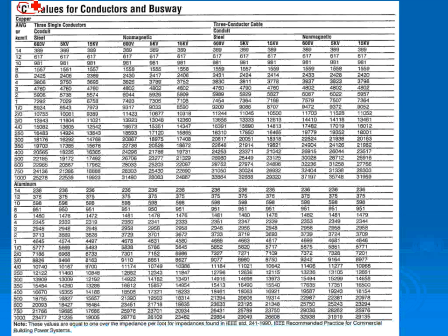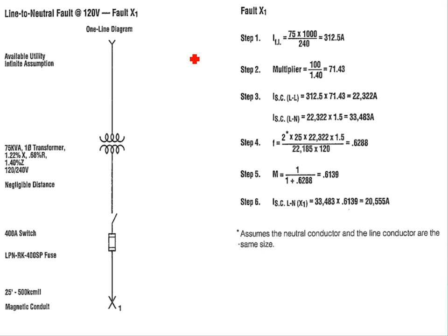So 300-400 feet away, you might end up with a smaller panel and cheaper circuit breakers inside it because the impedance of the cable will choke the current. So obviously we have to find the happy medium between them. You can't win with both. So these values are supposed to get you this. For a single phase, they do the same calculation.